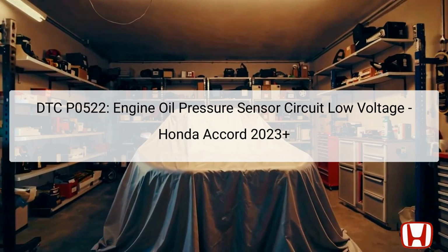The engine oil pressure sensor is crucial for monitoring the engine oil pressure, thereby ensuring that the engine operates within its optimal pressure range. If the sensor fails or reports values below a specified limit, the powertrain control module, commonly referred to as the PCM, records the anomaly and triggers this DTC.